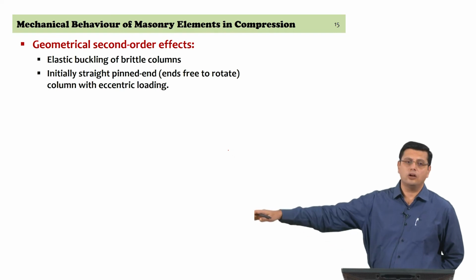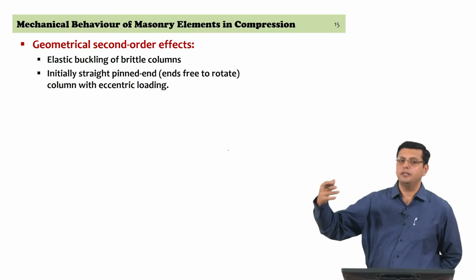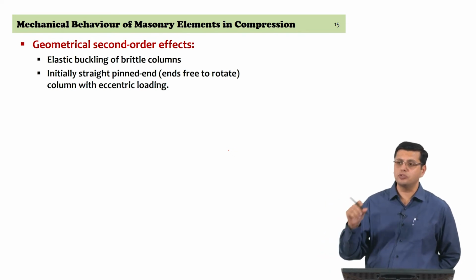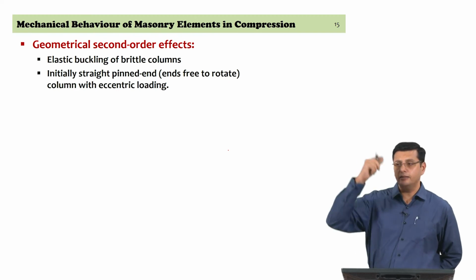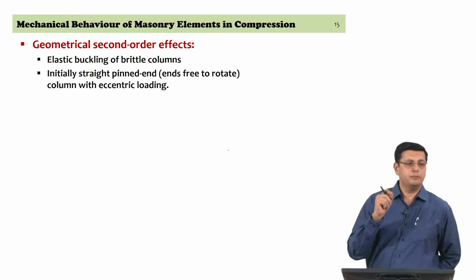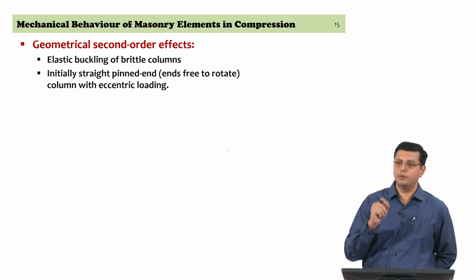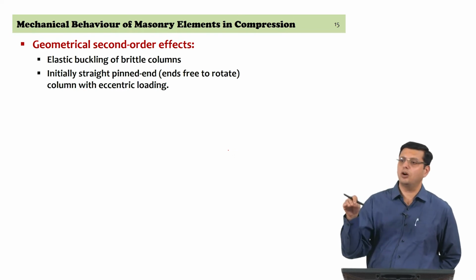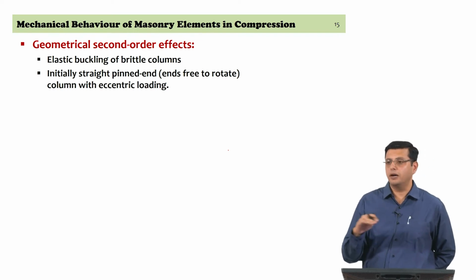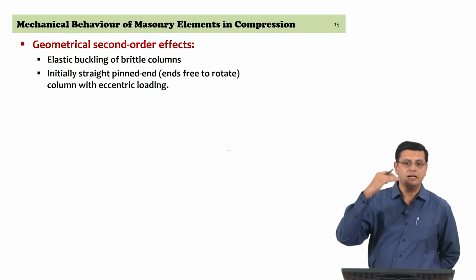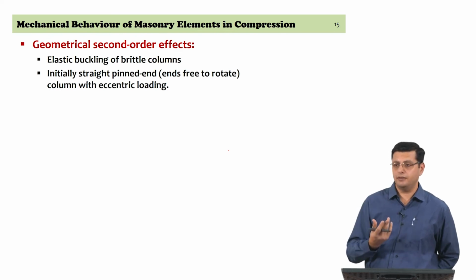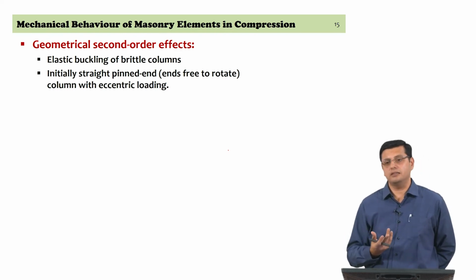You normally have a concrete slab that will come in at a certain point. If you are looking at the ground story and the plinth, you might have a damp proofing course. So, you would normally have a different material at the boundaries of the wall, and because you have different material, thermal expansion coefficients will be different, and that is sufficient to cause a cracking between these two surfaces. So, you can work with the assumption that you have cracked surfaces at the top and the bottom, allowing for some rotation, and therefore, the assumption of the two ends being pinned is rather acceptable